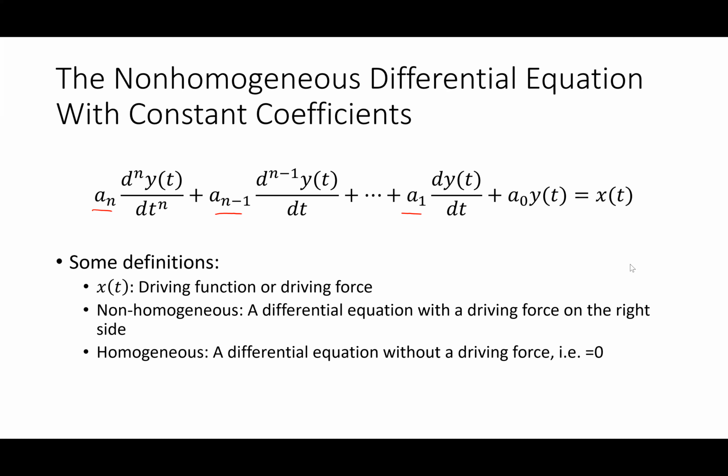So if I have one energy storage element, what order equation am I going to have? First, all right? If I have a second order system, I have 2 energy storage elements, okay? Today, we're going to get into second order systems. When I have second order systems, you can get strange behaviors that begin to happen.